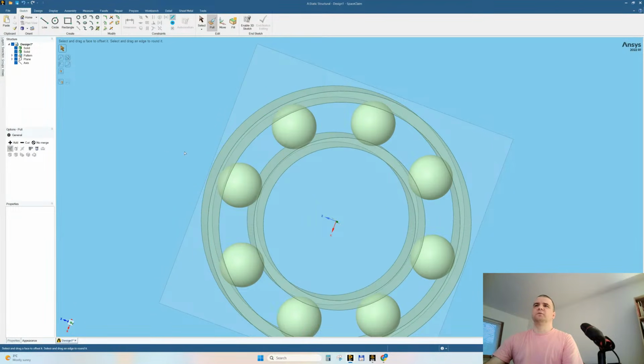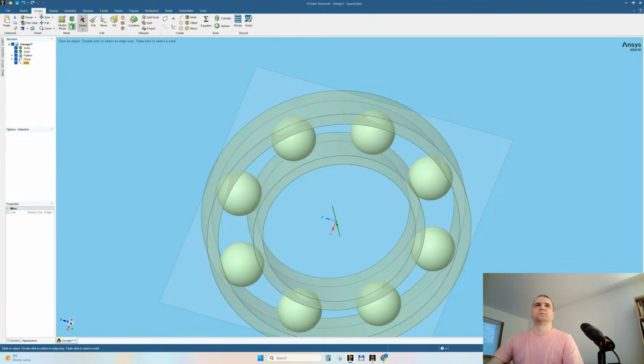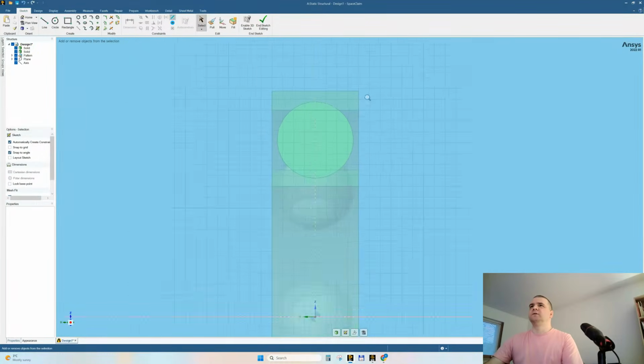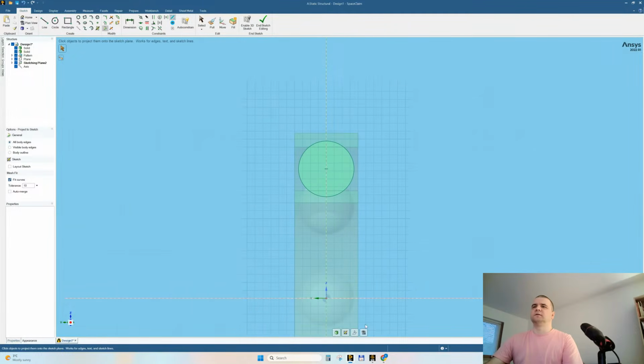All right, let's make the grooves in order to easier understand what happens. I will click the axis, escape, I will click the axis, then go to design sketch mode. Yes, so in principle, the easiest way is to project. I can project this circle. Yeah, let's do it. And I will rotate, cut both these races. You will see in a few seconds.